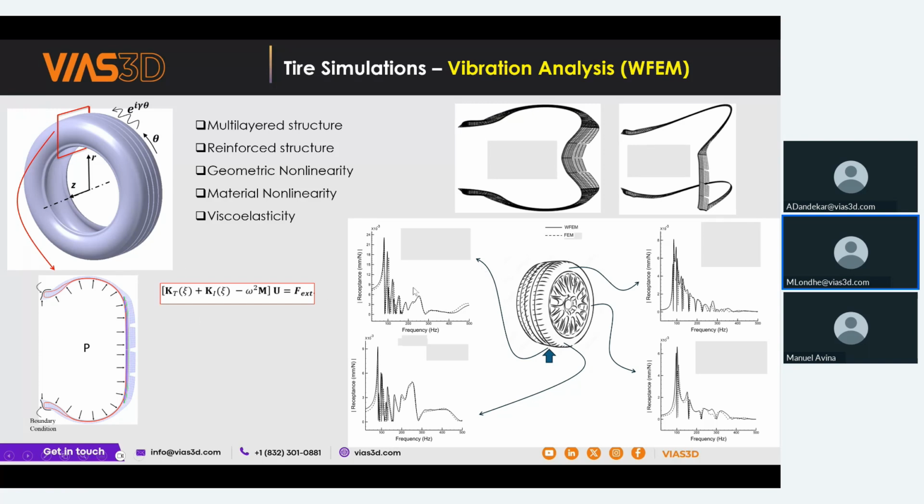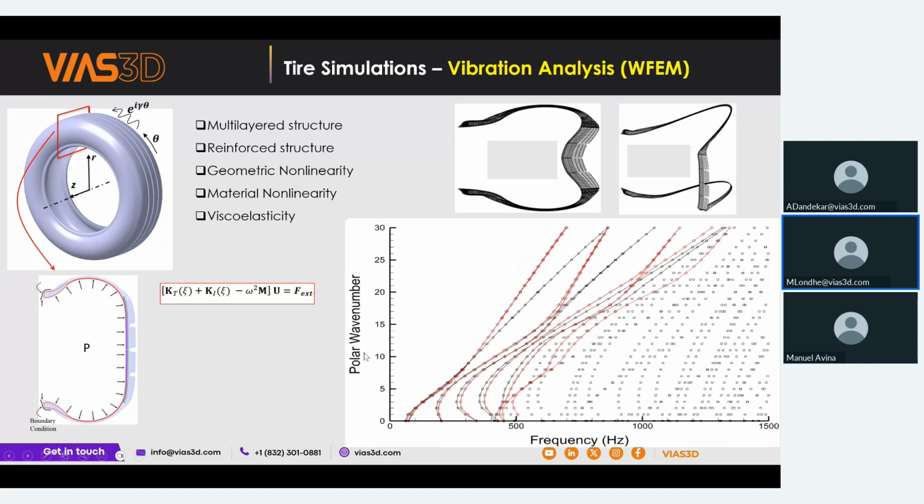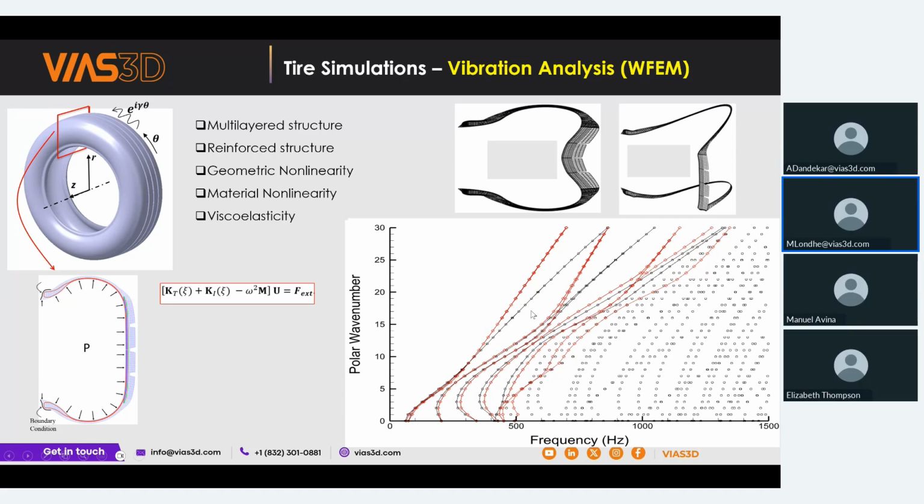And there is another aspect of this waveguide approach. Instead of analyzing each eigenvalue, you can analyze groups of eigenvalues, and those groups generally represent the wave characteristics, which travel along the tire. So when the tire vibrates, which waves are traveling, and which waves are damping out due to the viscoelastic damping. You can analyze this through curves of wave number versus frequency, generally represented as dispersion curves.